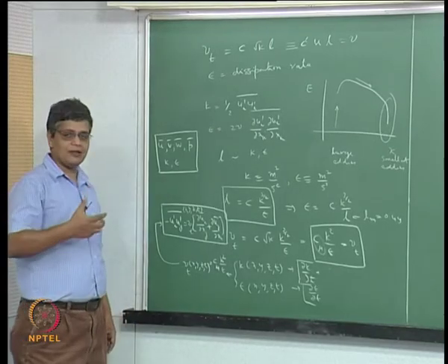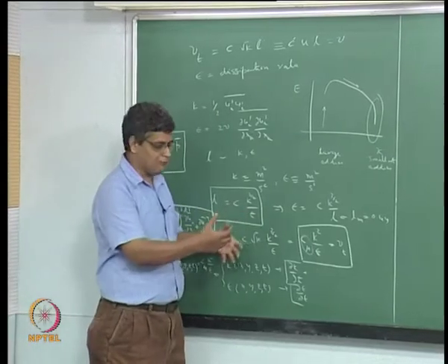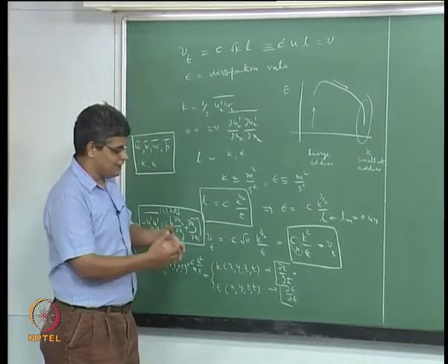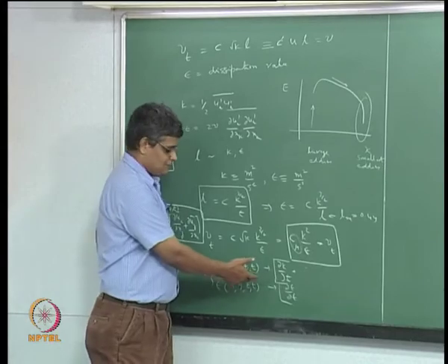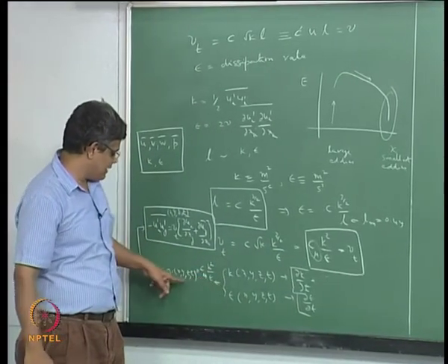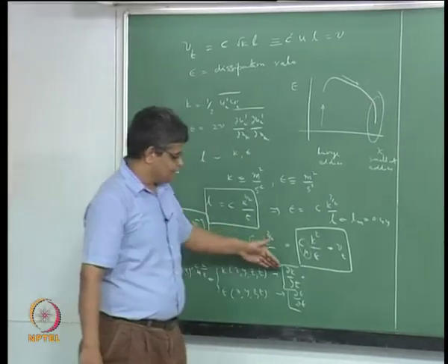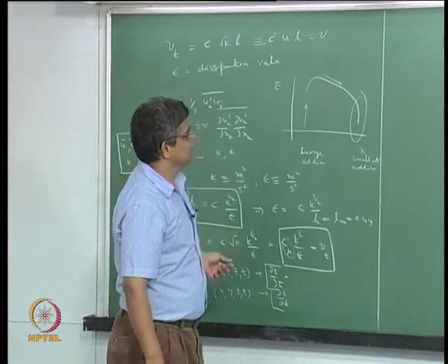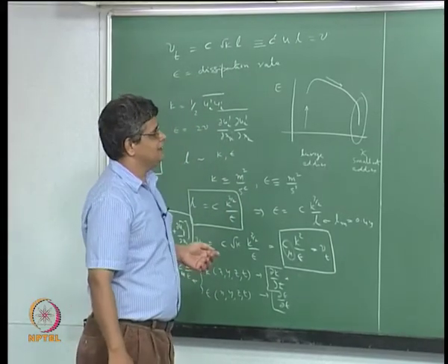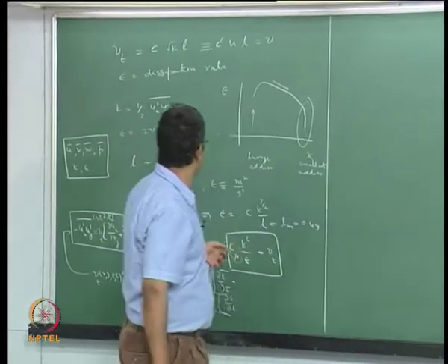All that template is already fixed, and we would like equations which go into the template which describe these turbulent parameters, from which we can get k and epsilon and then the turbulent viscosity. So how do we derive the equation for k and epsilon? We have already seen the basic idea for the derivation of k.